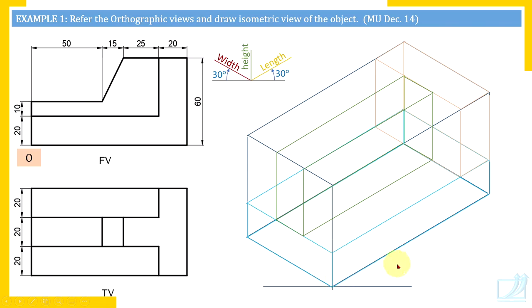Front surface. Why front surface? Because that is visible surface. So this surface. Let's make those edges dark. Now I have not made this entire edge dark because we can see that is front surface of this vertical plate and front surface of the base plate. They are in one plane. That is why there is no edge here.